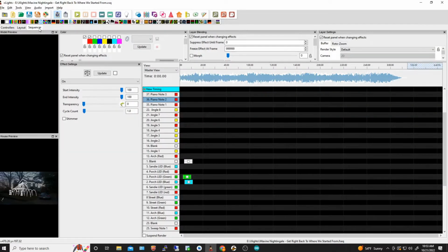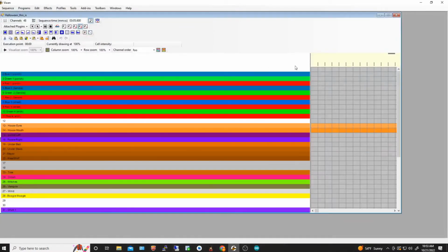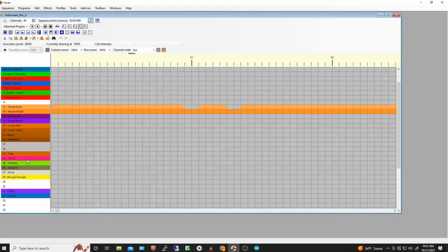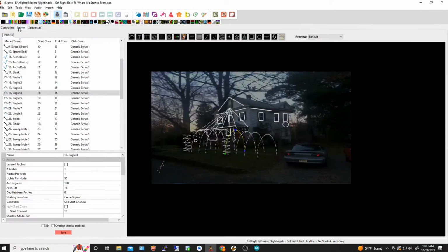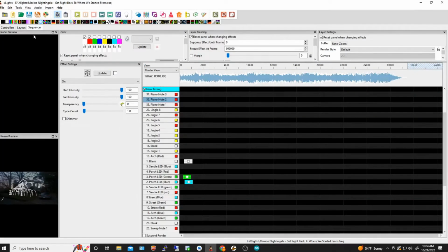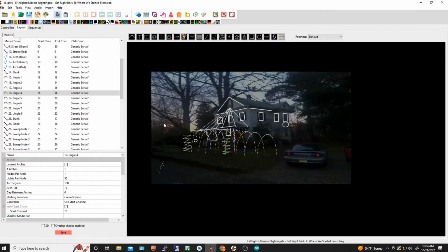So the last layer is a sequencer. Now in Vixen, remember Vixen, I have an old Vixen sequence over here. If you added different elements into your sequence, then you kind of had to go back and do every single one, you had to change almost every single script, and I guess that was a pain in the ass, right? So in this situation, you have your layout. Your layout is kind of done, and now you can build lots of different sequences on that layout. And if the layout does change, or if you add some things, you can change your sequences. You can import values into your sequence without screwing everything up.